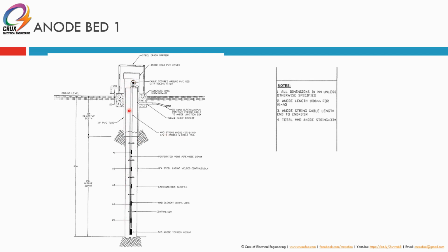So normally when you do the drilling for your anode bed up to 30-40 meters, you will also use your drilling as part of your soil survey. When you drill up to 5 meters, you measure the soil resistivity at 5 meters, then 8 meters, 10 meters, then up to as deep as you want. Then you'll know which depth has the best soil resistivity, and to size your cathodic protection.